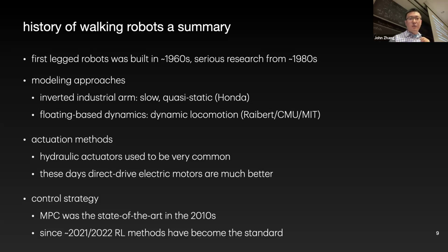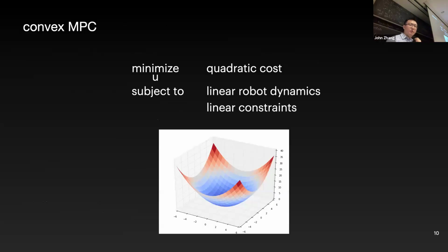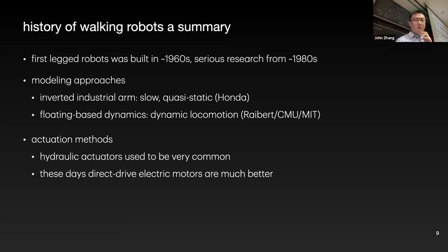So that's that. The first control algorithm that we're going to, yes, Gary? Could you tell me a little bit about the quasi-static there? Quasi-static means you're assuming your robots are moving really, really slowly, similar to industrial robot arms that move like this. That's what they were doing. So the velocity is zeroed out. We're assuming the velocities are really small, and sometimes you can throw all the velocity terms into your mass matrix, for example.